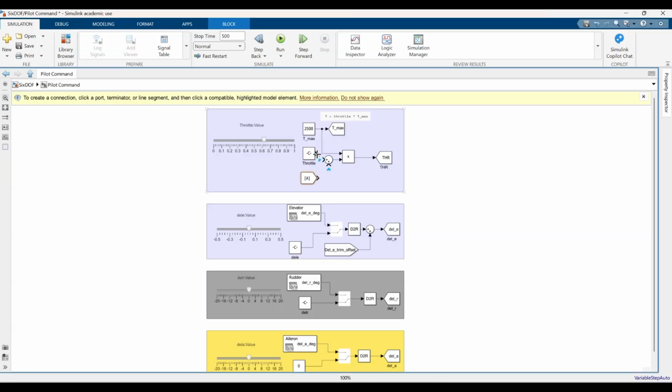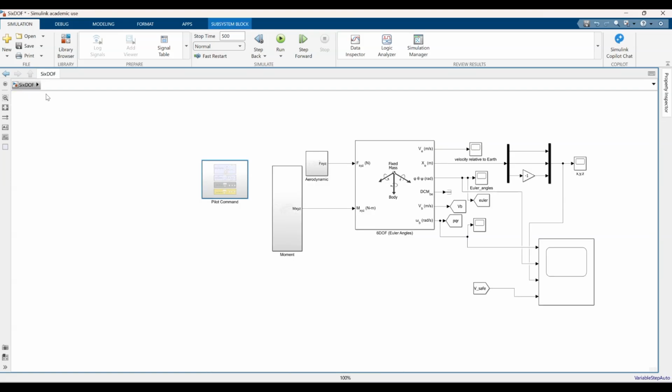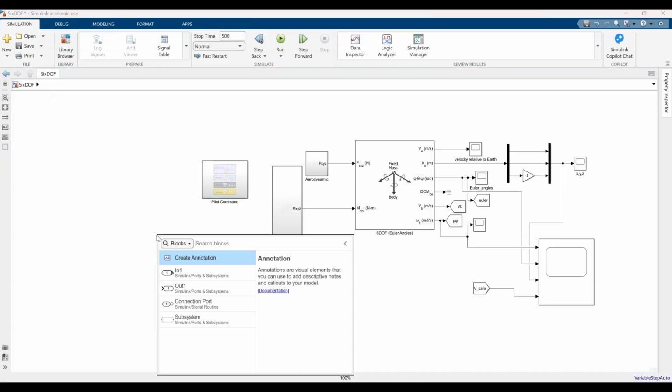Now we have done another episode on the elevator trim, if you remember, and that was episode 5, I believe, that we designed. It was the trim wheel design kind of concept. So what is available in the cockpit had nothing to do with this equilibrium solver design. So it may look similar to that, is what I'm trying to say. So this del E trim offset, if you remember, comes from that other elevator trim wheel algorithm. We will change that to the equilibrium trim as well for now. And later we will develop the autopilot system a little bit later.